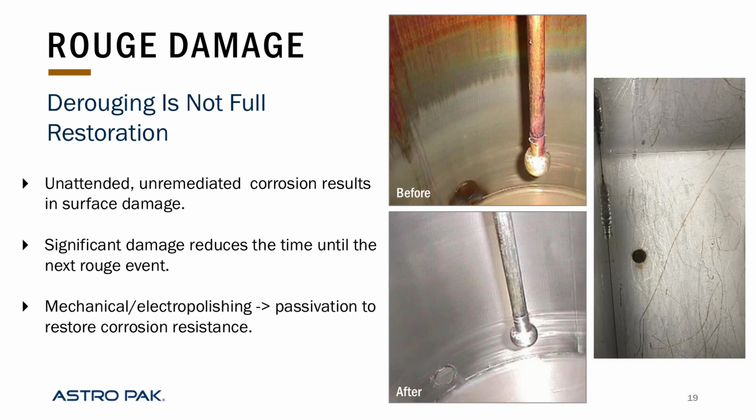They clean it with 1,000 ppm bleach. It's fine to clean all other surfaces and some of the superficial scratches, but this scratch right here, it was deep enough to where the 1,000 ppm bleach generated rouge. It was not drying quick enough, and just within this scratch, you were having some corrosive chlorine still remain. Taking a profilometer to this, I got an RA across it of 24, and there are other parameters in the profilometer. There's R max, RZ, another one RT that I'll talk about in a few slides. Those were off the charts when I took the profilometer across it, but the average was still fine.